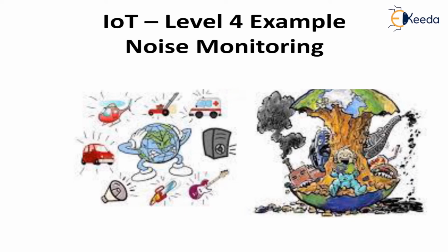The measurements are transmitted to the IoT platform to monitor the noise once registered, and they are available in real time by means of user applications. The database receives and stores the data related to noise from terminals and from each sensor, that is, the sound level sensors, and it does the most monotonous and repetitive tasks: time-based recalculation, day, evening or night calculation, analysis of incidents, comparison with regulatory limits, email alerts, data download, and creation of reports. These are all possible in noise level monitoring.